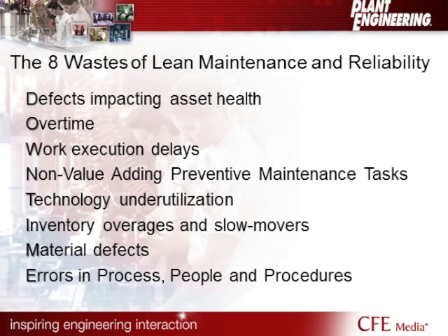Material defects, the M in DOWNTIME. Now we're talking about how we store those parts, how we store in-process goods. All of those can lead to the defects that get into our system. How many of you have had a bearing that someone took out of the grease paper and then put back on the shelf in the storeroom? Then when you go to get it and use it later on, you notice their fingerprint on that asset. So that's a material defect. We install that into the piece of equipment. There's a pretty good chance we're going to have problems out of it at a much faster rate than what we would have if it had been in like-new condition.